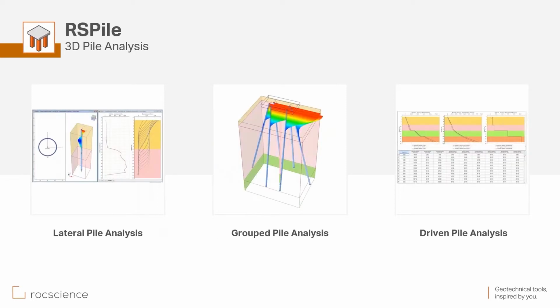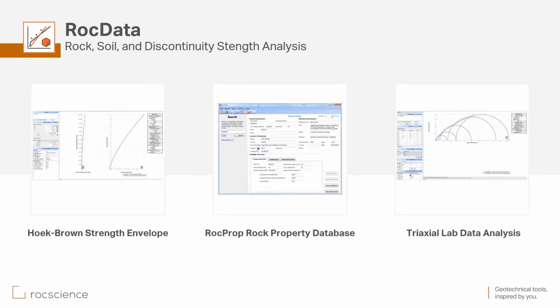liquefaction analysis. RS-Pile is one of our newest packages. With this one, you can do pile analysis, individual pile analysis, or group piles. You can do lateral pile analysis, and also driven pile analysis. And with the integration of RS-Pile with Slide2, using this interaction, you can evaluate the support forces of piles accurately and use them in your slope stability analysis.